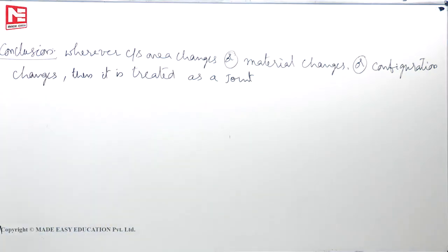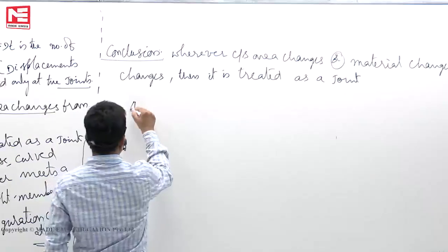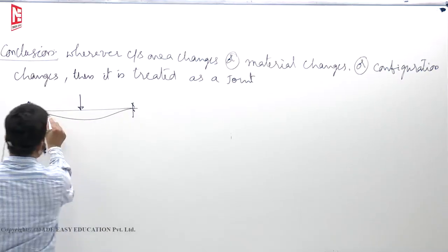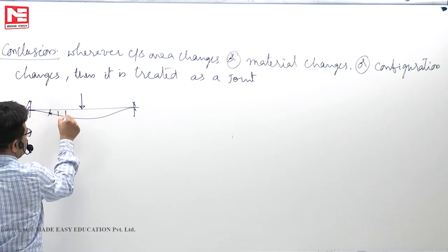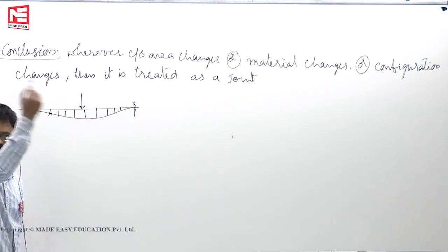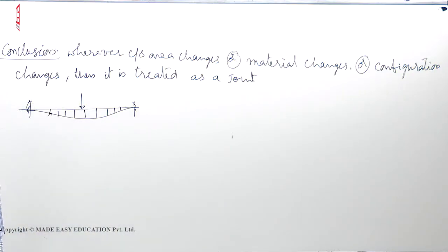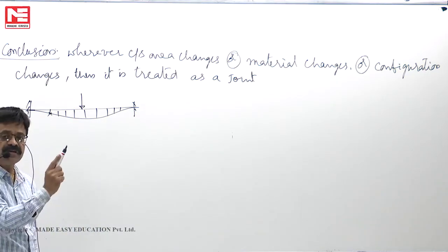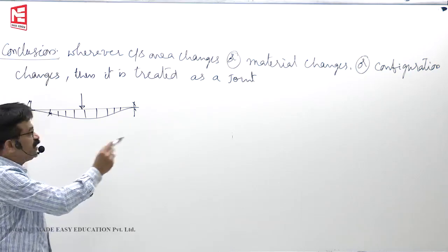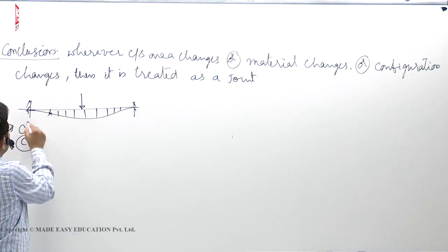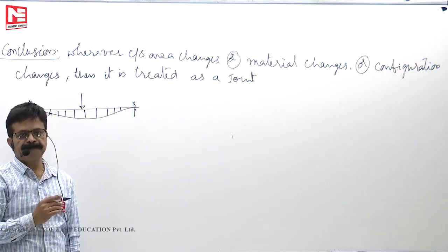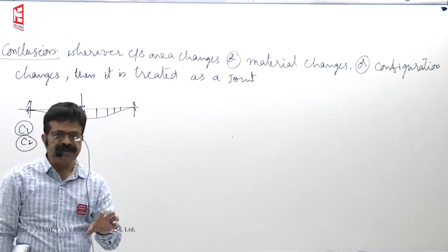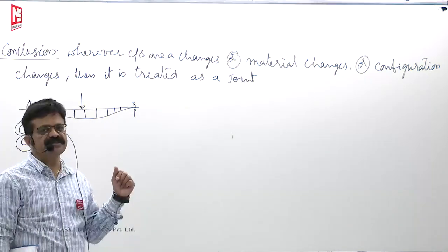Otherwise, everywhere, if you have a fixed beam like this, say, subjected to some load. Here, independent displacement, deflection is different like this. Infinite number of displacements are unknowns only. But entire curve I can define with a single equation. So they are no longer independent. They are all dependent on C1, C2, constants of integration. Okay. So degrees of freedom means number of independent displacements only, we call them as degrees of freedom.